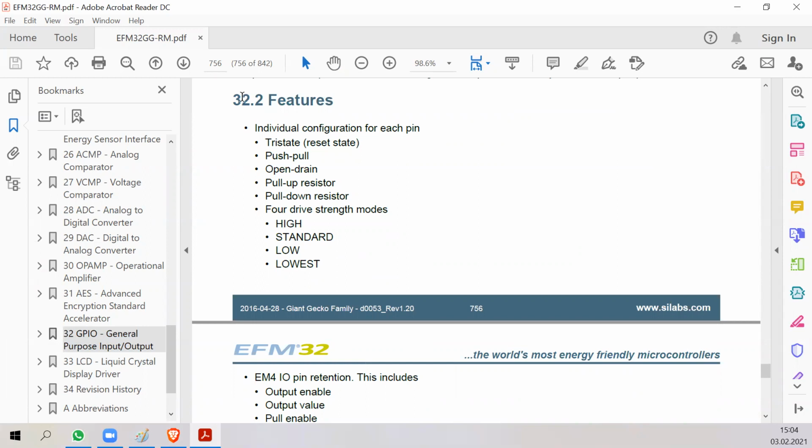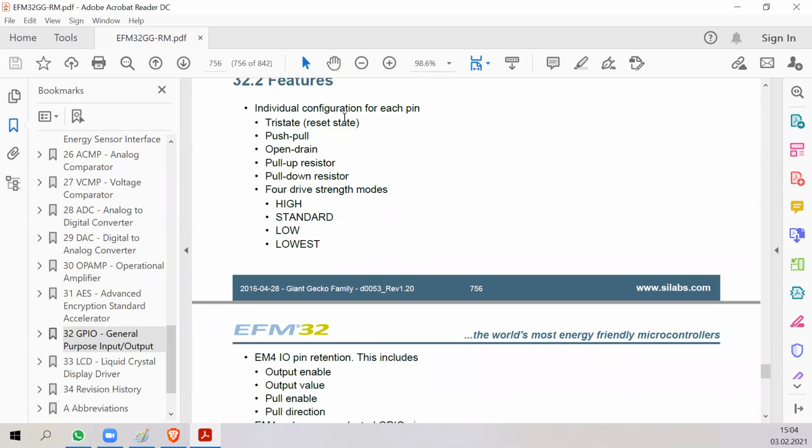So this microcontroller, for example, when you reset it, all pins are inputs, so that if you have connected some switch, the microcontroller doesn't switch the switch on or off. It's just an input, so it's off. And if you want to do some switching, you first need to set it to output. And in this microcontroller world, output is called push-pull, because you either push the output high or pull it low.